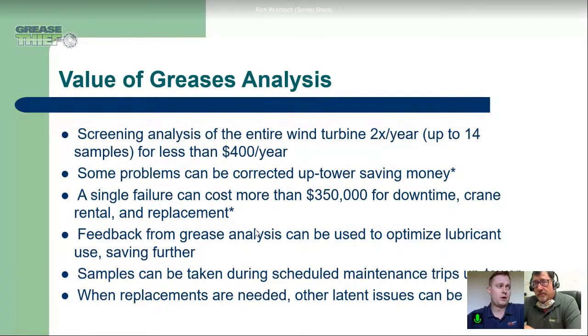So if you are considering doing something like these proactive hot oil flushes, taking grease samples before, after, and throughout can help validate whether or not you are protecting the component and getting more remaining useful life out of it. And that's the end goal.